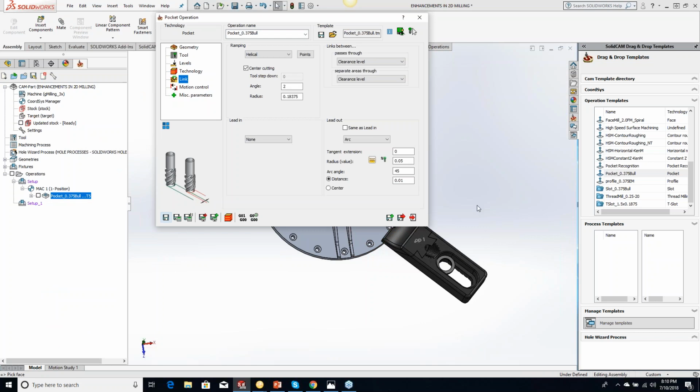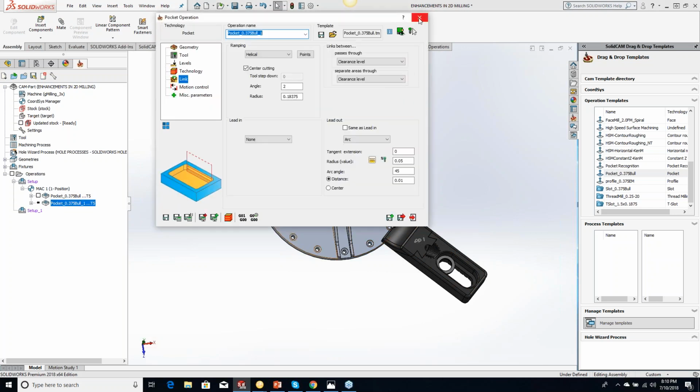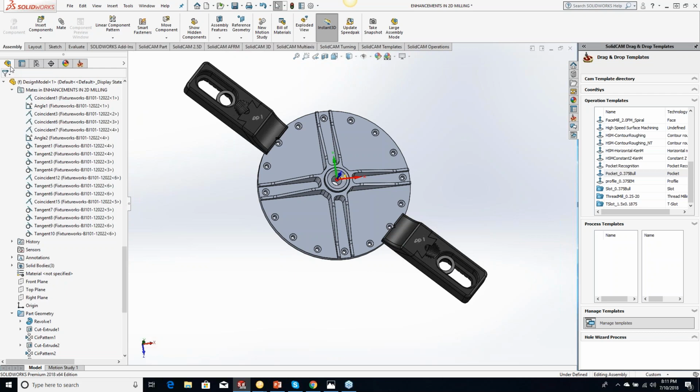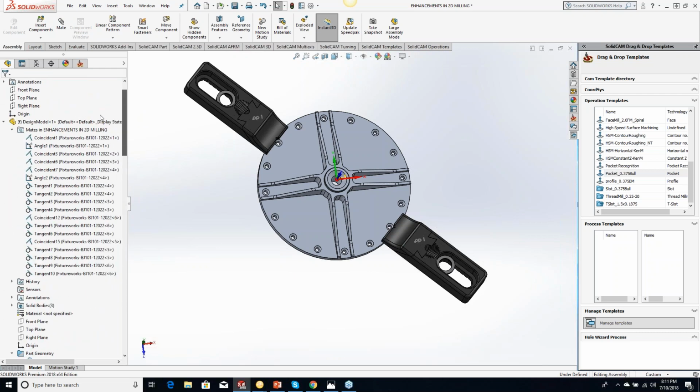And now what we're left with is those other pieces that are left over. So what I can actually do from right here is a save and copy. And I'm just going to exit out of here and drag that operation below my setup. So now I've dragged that below my setup. Since I have cut rest material only and avoid the fixtures, if I come over to here, and let's see, I got so many in here.